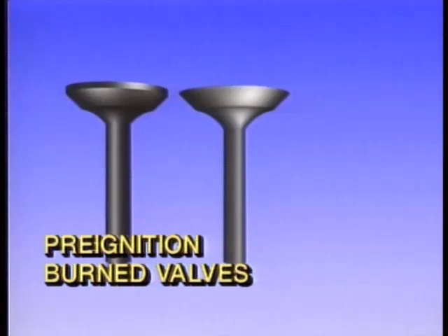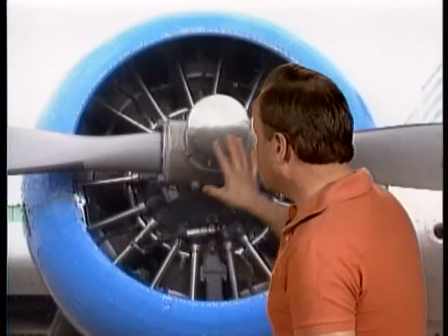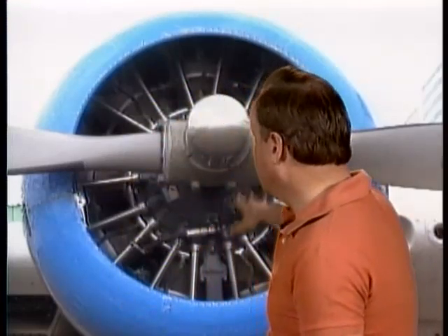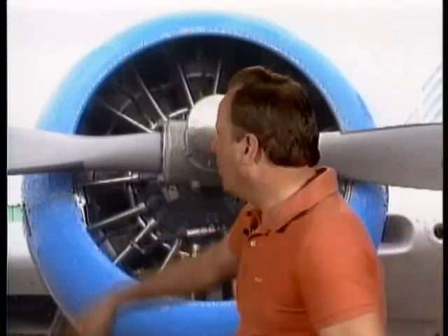All right, let's talk about oil. Oil is pretty important, you know that. So let's assume that you're overhauling an engine with a dry sump. By the way, a typical engine with a dry sump might be a radial engine. The FAA wants you to know before you run this engine, it'd be a good idea to what is known as pre-oil that engine. So you should pre-oil the engine. How do you pre-oil the engine? Well, you take the oil lines and pump oil into the engine to make sure that you have oil all throughout the engine. Now, how do you know that you have the engine sufficiently pre-oiled?